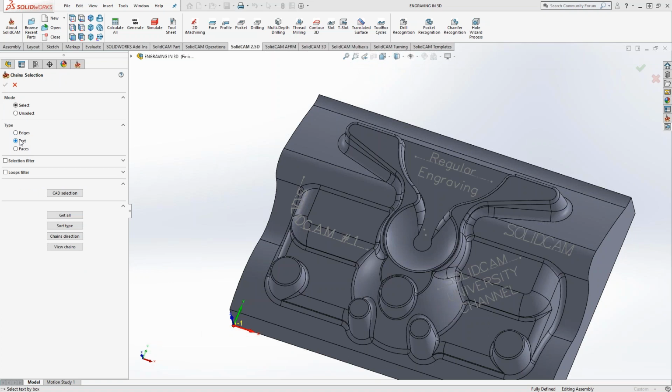So that same idea of grabbing one piece of geometry and then filtering that into what we need, this is what this basically does. I say I'm looking for text. I'll go to my text right here, and if I hover my mouse over there, it recognizes that as SolidWorks text. And once we do this, I'll show you how we actually generate SolidWorks text versus text inside SolidCAM. But basically, it's a form of geometry that we know as text.